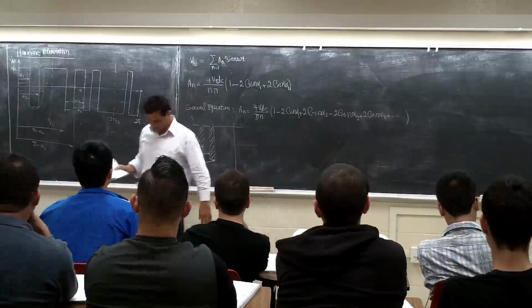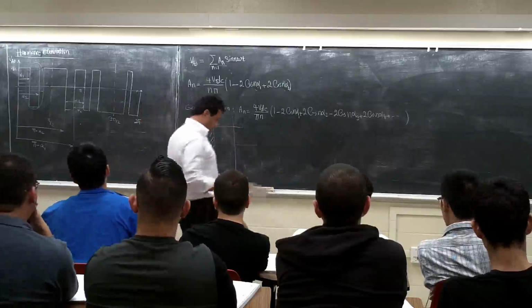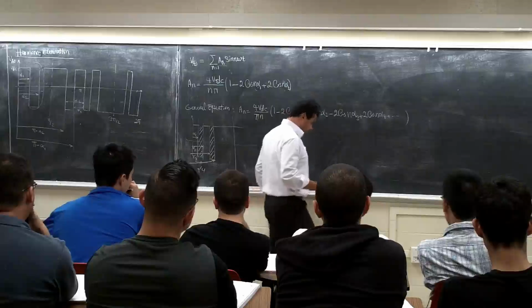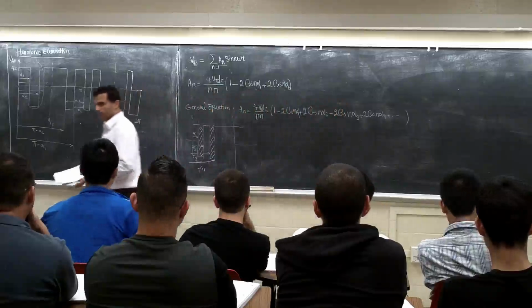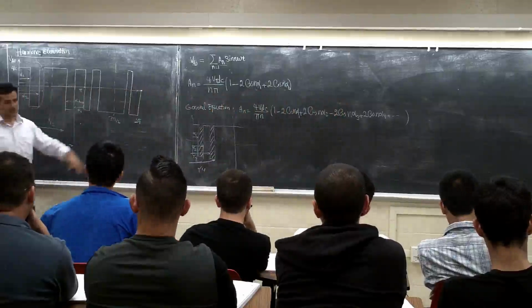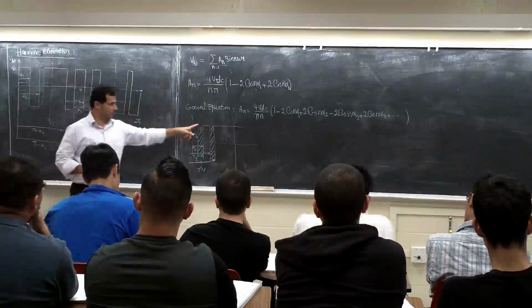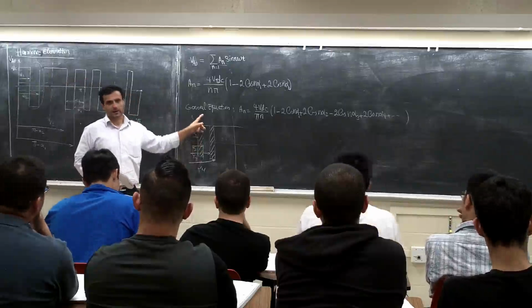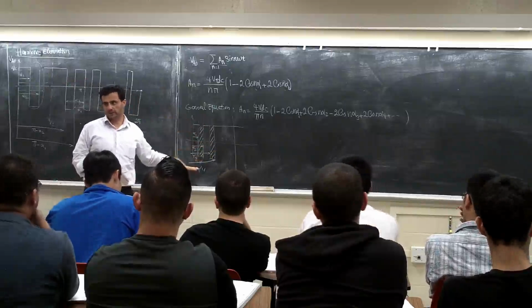So basically having more notches is going to give you more control over the output voltage, to become a better sine waveform. But what is the problem with more notches? Every notch means a switch, right? Every notch, boom, coming here and going back there. This is like a bipolar switching, right? They're going from VDC to minus VDC.